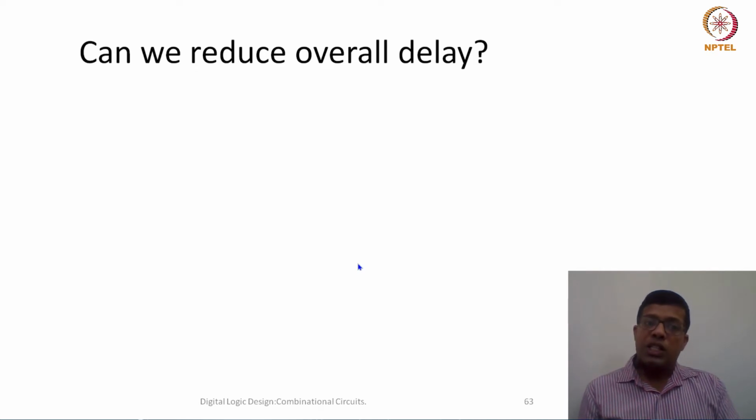These days in our computers, most of the computations are 64-bit computations, which essentially means that the delay of this adder would grow linearly as we grow the size of the addition. That could hugely impact things, because addition is a very fundamental unit in any digital design. You would require addition invariably in most circuits. So if the delay keeps increasing as the size increases, it's going to be a very costly operation. So it's very important that we reduce the delay of this addition.